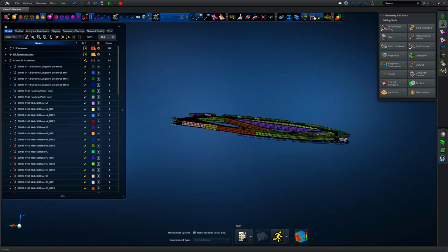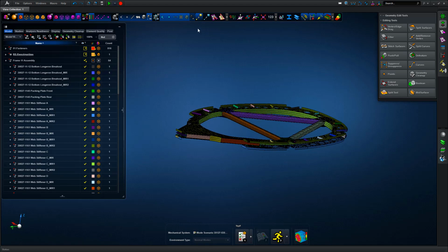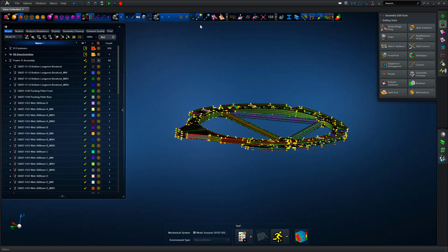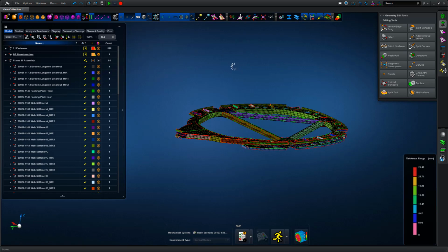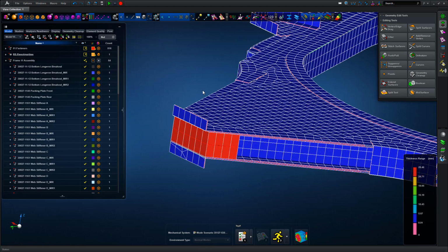So once we've got those mesh edits done, we can check the shell thickness definition, by putting the surfaces on and looking at the 3D representation of shell thickness, just working its way through this set of property sets.